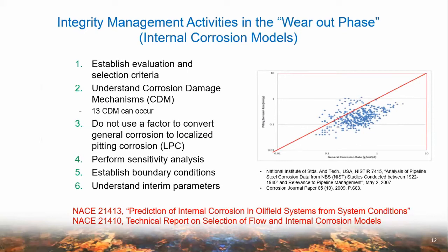In my opinion, using general corrosion rate to predict pitting corrosion rate is analogous to buying a lottery ticket and starting to spend the money assuming that you would win the lottery. The odds are very, very low. If we can take one message out of this webinar, it is this one: do not use general corrosion models to predict pitting corrosion rate.